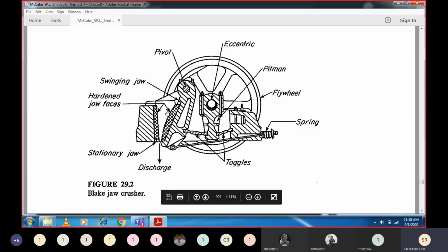Remember this. Now this concept is not there in the dodge type of crusher. Because in the dodge type of crusher, this size, this 1 millimeter size, is fixed. Unless the size of the particle is less than 1 millimeter, it cannot go from the bottom. Till then, it will be staying inside the system, occupying the space. Since it is occupying the space, it will not allow other particles to come in.